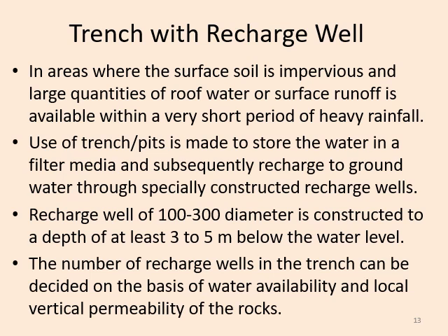Why is it written here rock? Because the soil is impervious, and rock is also impervious in nature. So where there is a rocky geological formation, there also we can use a trench or pit with recharge well.